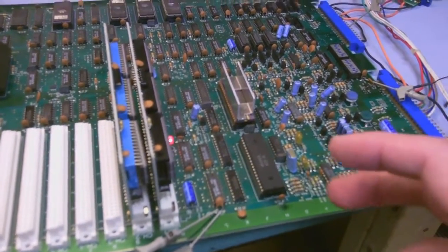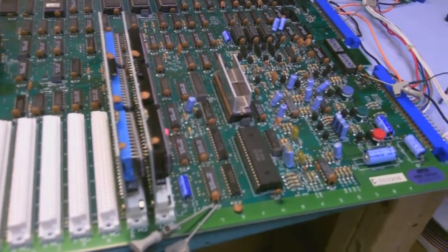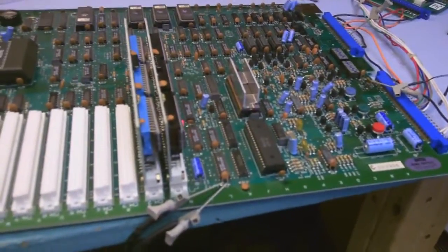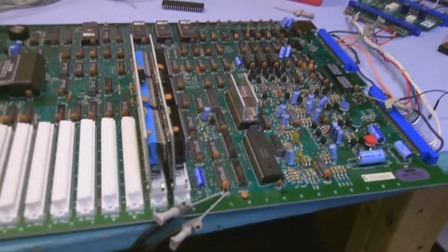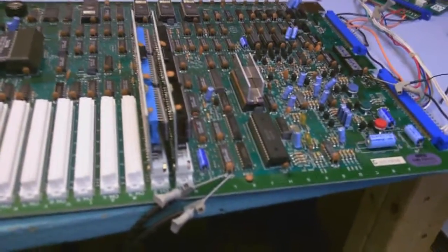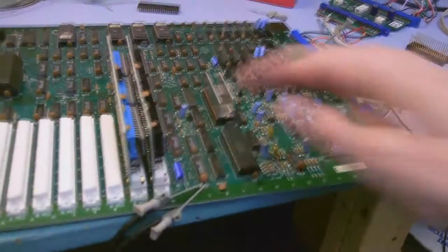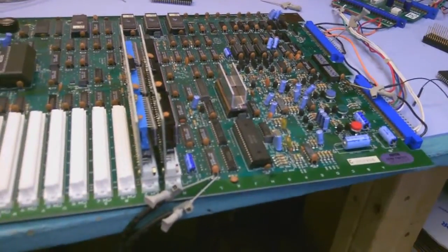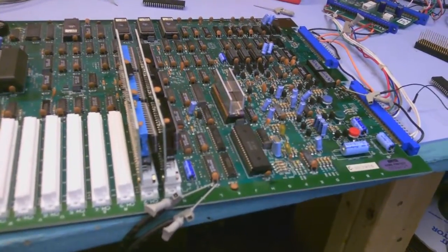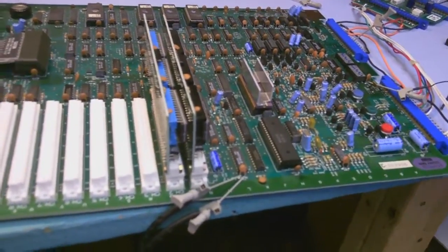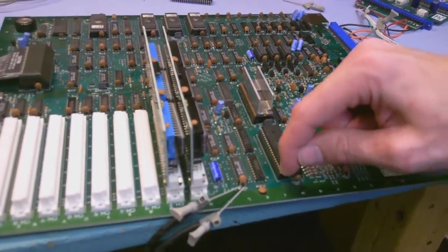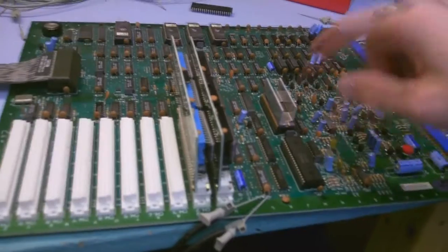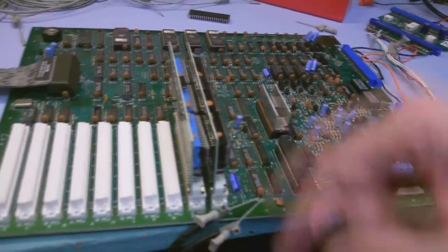Okay, so basically what I did was pull all of that junk off. I mean, actually, it was very neat work, I should say, but they were all wrong, I think, with the exception of one, maybe two traces. And so kudos on the attempt, but maybe they just lost track. There was quite a bit of congestion with all the traces going under the board, and so it was very easy to get lost. And so I ohmed them out with my ohm meter, and realized that almost all of them were wrong, and so I just pulled them all off and redid them all. Anyway, everything on this side flows down underneath the PCB in that direction, and that's where that big scrape was. And so just for a sanity check, I traced every single one of these out to make sure they were all okay.